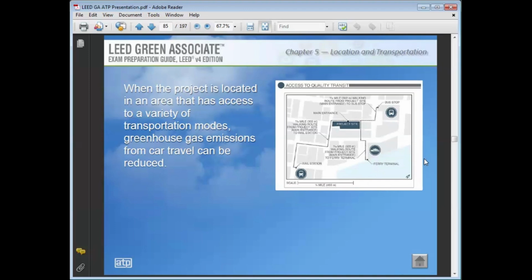So you utilize that to fulfill all of those requirements, number one. Number two, have ample open spaces on the ground floor level, on the surface level, so that the rainwater can infiltrate back into the soil rather than letting it go out through the stormwater drain channels. Because in that way, the context-based water level will start declining. If you have some pervious surfaces through which water can penetrate downwards into the ground, that is something which is acceptable. Just like in the later stage in water efficiency, you will be studying rainwater harvesting, which is a very good tool towards understanding how these parameters have to be established.